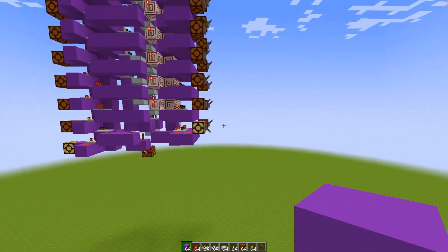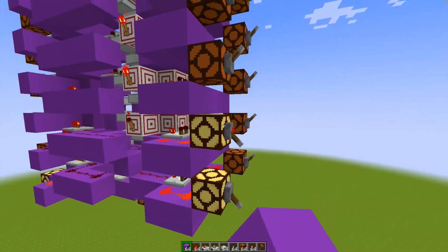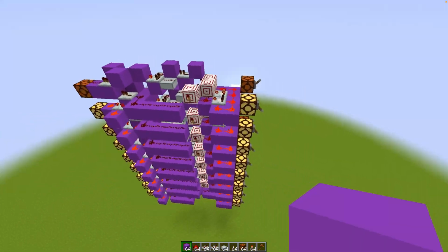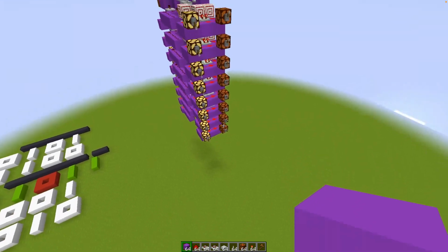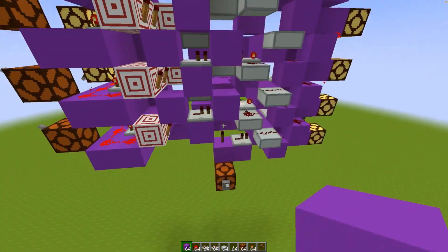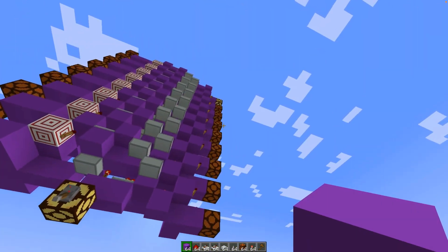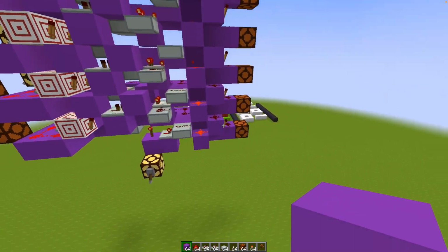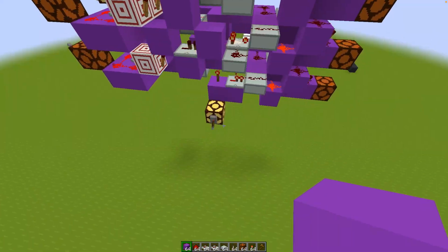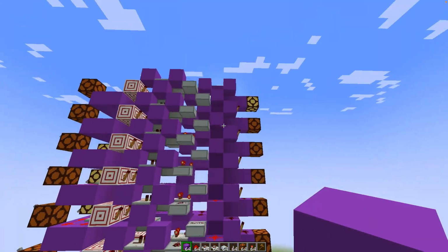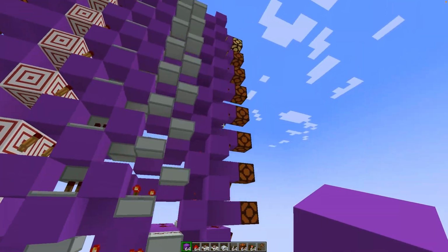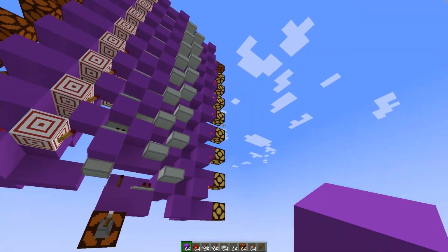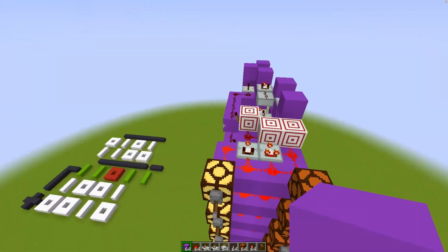As you can see, the input just flows right through. If I turn on all of these, then we have 255 right here. If I then turn on the carry in, then it's going to go to the carry out. As you can see, if it was a ripple carry adder, it would do like 3 seconds per bit. It would be incredibly slow, but this one calculates them all in parallel, which makes it a whole bunch faster. And the same goes for the folding edge. There we go. Okay, so let's build this guy.